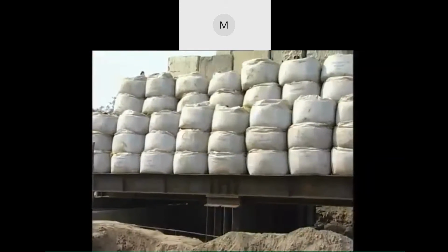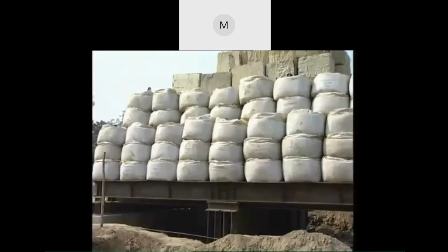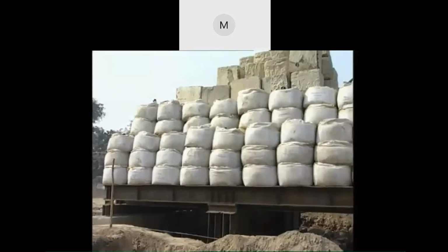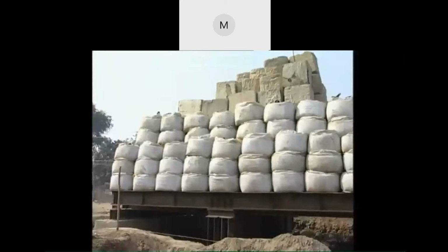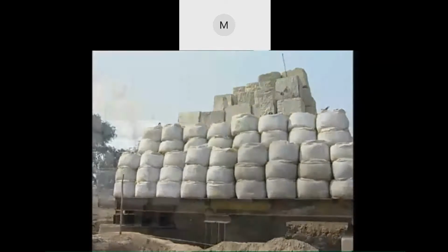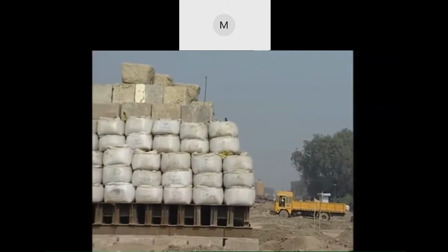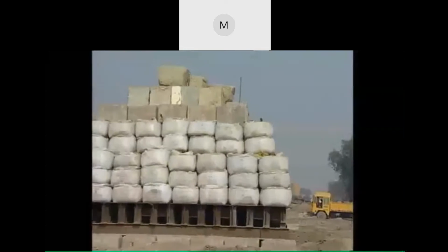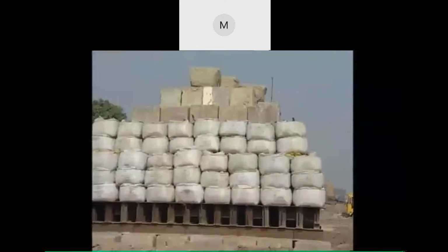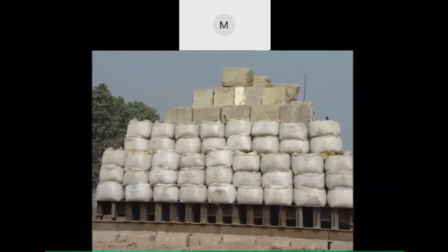The vertical load is applied by a Kentledge in the form of jumbo sandbags, each weighing 1 ton, in 9 tiers corresponding to a total load of 850 tons placed on a platform erected on top of the pile.